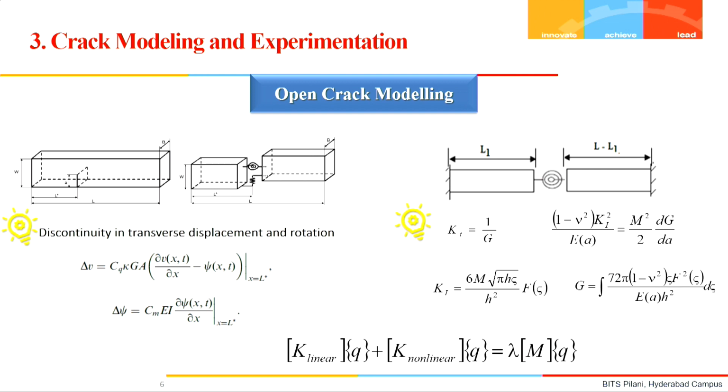Furthermore, we have also found that the system's total strain energy, after considering the springs, the contribution of this extensional spring is insignificant compared to the torsional spring. That is because of the flexural vibration. Most of the structural elements are subjected to flexural vibrations, and we are talking about flexural vibrations. So the contribution of the extensional spring can be further neglected because the effect of in-plane shear in the open crack is very negligible compared to the opening mode, the first mode.